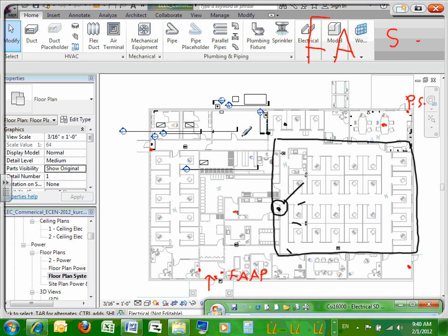Corridors for horn strobes or for pull stations? I think just at the exterior exits. We don't need them throughout the corridors. Joe, don't they have, I think there's something, 100 feet? If you're 100 feet or more, you pull them. I can't remember. We don't have it in this situation, but if you have a big hallway or corridor, I think every 100 feet, if I remember right. You need to be so far away from the pull station.